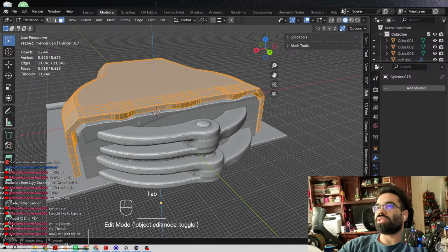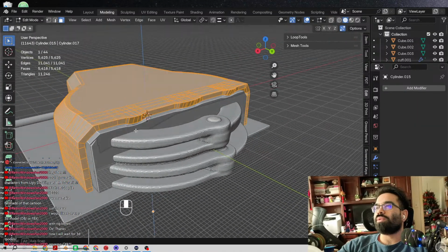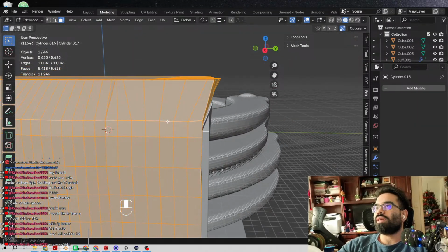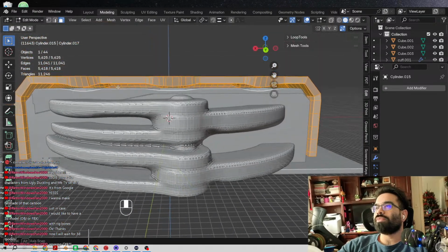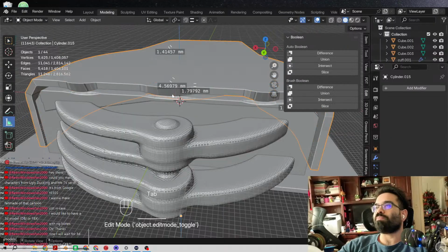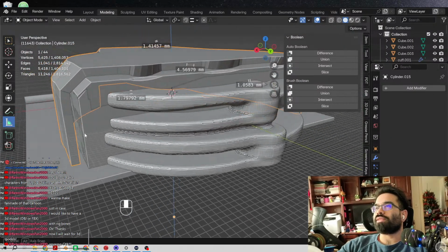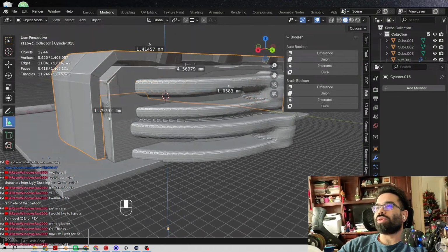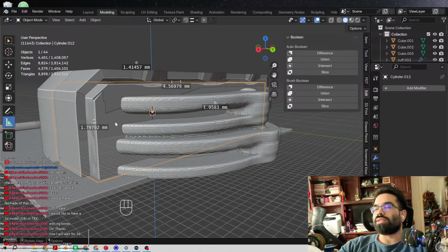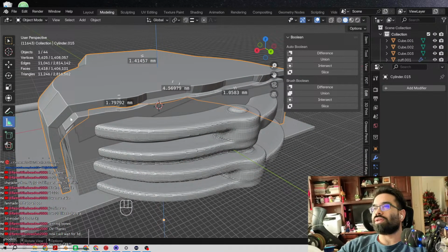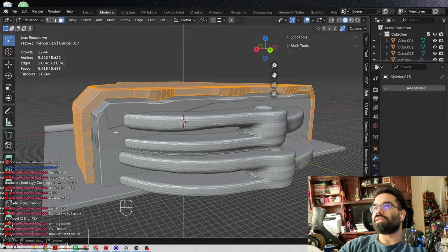We got to make changes to the design of this cap too. And the way we're going to be doing that, honestly, all of this needs to be redefined here, but we'll be using the same. We just need to make this thing beefier, because he uses a thin plastic for this, and he has to heat it up and melt it over this. And since this is 3D printed, any thin plastics here are also just gonna get melted. And I can't have this thing melting.